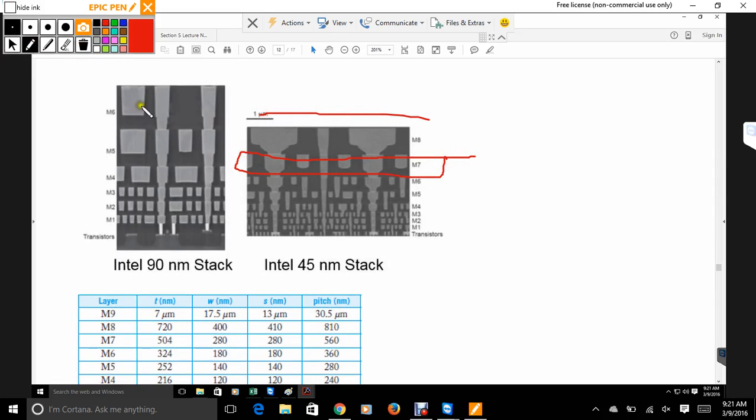So your top layers are going to be these guys here. And if you recall what I mentioned earlier about the thicker wires having the least resistance, you want that supply voltage to have as little resistance as possible because you want it to get there, and then everything else you deal with, how you design your transistor cells and how they communicate.